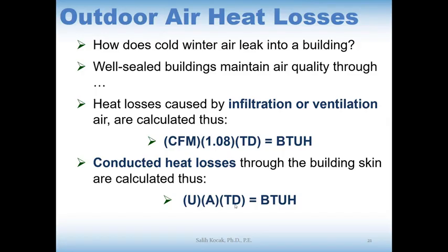And if I need to give you an example with the use of infiltration and ventilation, let's think of a building which has an infiltration rate of 4,000 and a ventilation rate of 6,000 CFM, and let's calculate the BTU heat losses when the indoor temperature is 70 and the outdoor temperature is, let's take it 0 now. So indoor is 70, outdoor temperature is 0. So the temperature difference here is 70 minus 0, which is 70.